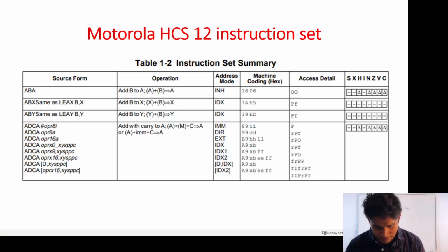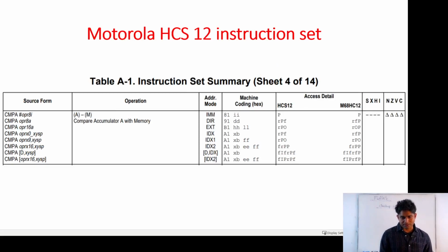All right, let's do that. And I wanted to also show this. This is again the instruction set, which shows the compare operations. So CMPA is again a code. It's basically an assembly language code, a mnemonic. We call that a mnemonic. Compare A. A is the temporary register or memory location that is present within the CPU. And in this particular operation, you're trying to compare the contents of A with the content of the memory location that you provided.